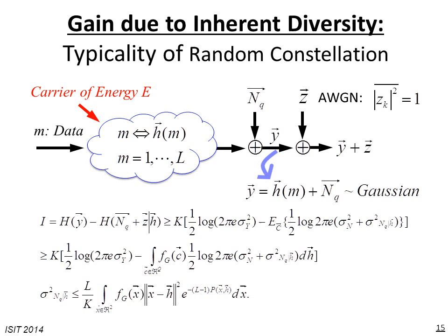But please, I repeat again, it's not 2K parallel channels, because 2K parallel channels would require 2K units of energy at the transmitter. Here we transmit 1 unit of energy over I, 1 unit over Q, or 1 unit of energy over a complex coordinate system at the transmitter, and we receive independent units of energy with independent information over each receive antenna. So we send 1 unit of energy and we have a factor of energy harvesting of K.